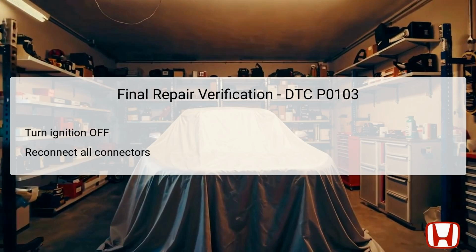Final repair verification is crucial for confirming the effectiveness of the repairs made. Start this step by turning the ignition switch to the off position. Once the vehicle is off, ensure to reconnect all connectors that were previously disconnected, including those for the MAF sensor and PCM. Utilize the HDS to exit the SCS mode and perform a reset of the PCM. This step guarantees that any previous settings or errors from the past operation are cleared.